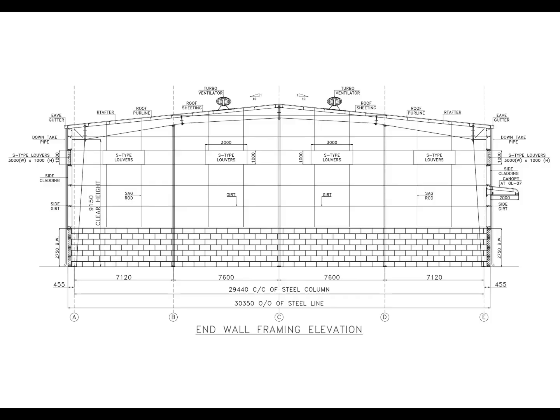In our real project drawing, we can see how the horizontal wall framing members work together with the vertical framing and other components. This is the practical difference between learning a definition and learning how to read an actual PEB structure.